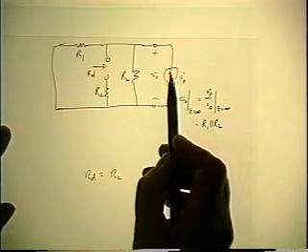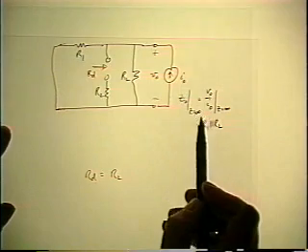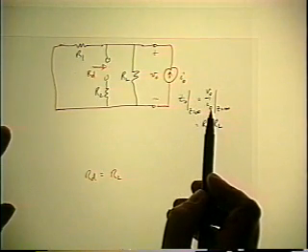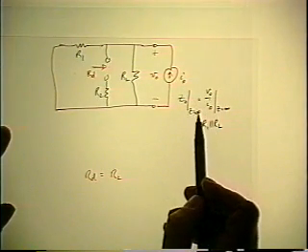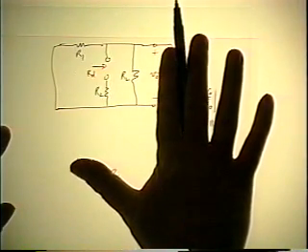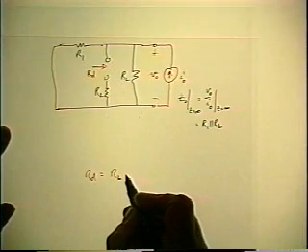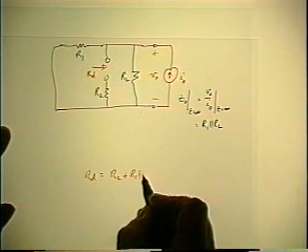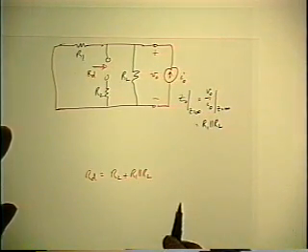And the correct identification of the input is IO, because that's the quantity in the denominator of the transfer function. So if IO is 0, that current generator is gone, and so you're going to get R1 plus RL for the RD.